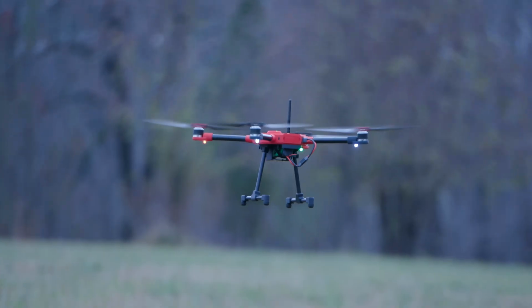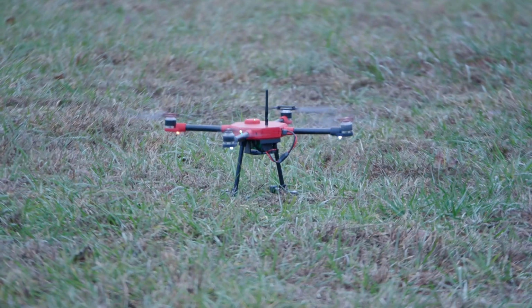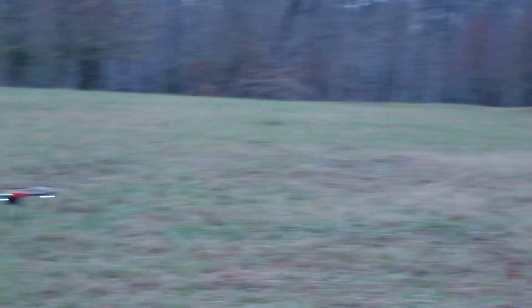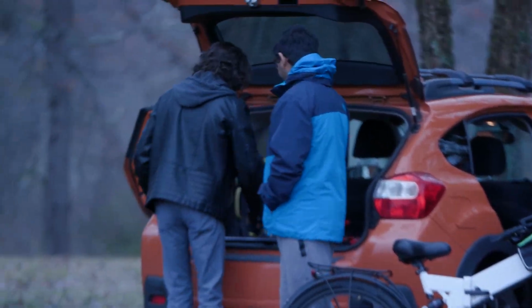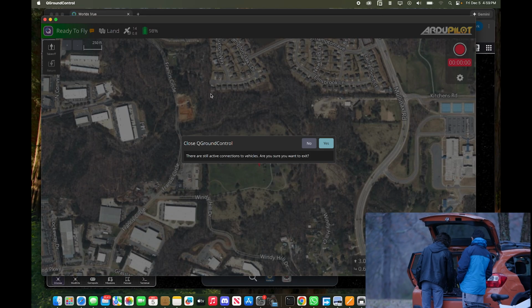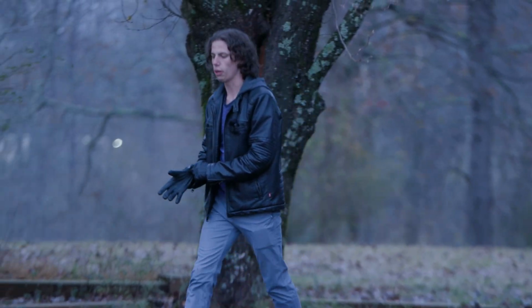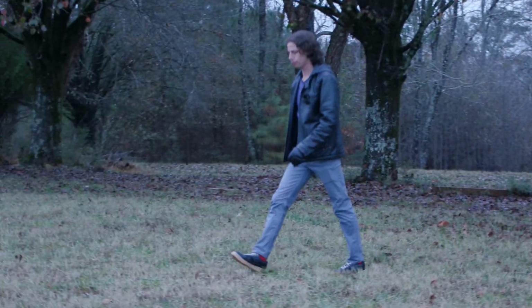So we are seeing flight. Some of that could be, a couple of these motors are a little tilted, but nothing that the flight controller can't compensate for clearly. Before we go ahead and take off in the iVue RC app, let me just go ahead and do a quick review, make sure all the motors aren't too far out of whack.